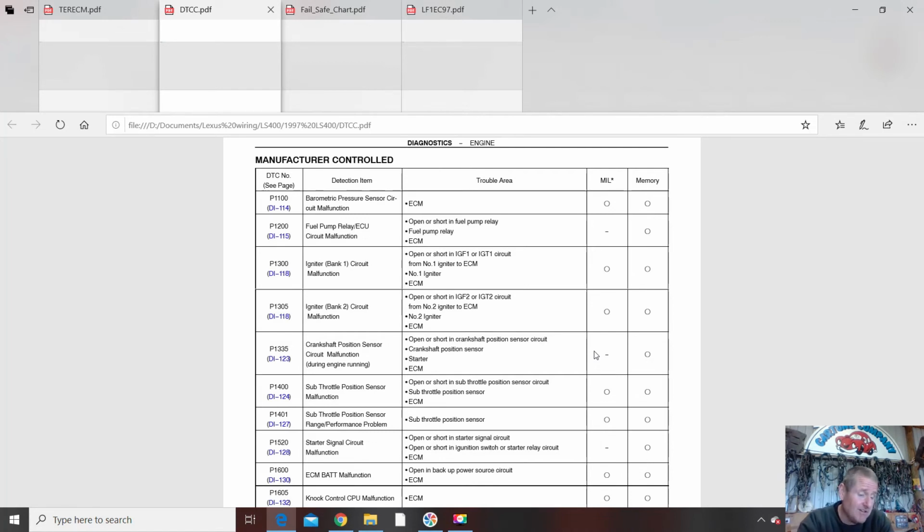Another one for the Aussie guys, your VE Commodore. I think they've got about 60 conditions that will cause a fault code, but only something like 36 of them bring on an engine check light. One of them is the airflow meter isn't plugged in or isn't attached. Doesn't bring on a fault code.